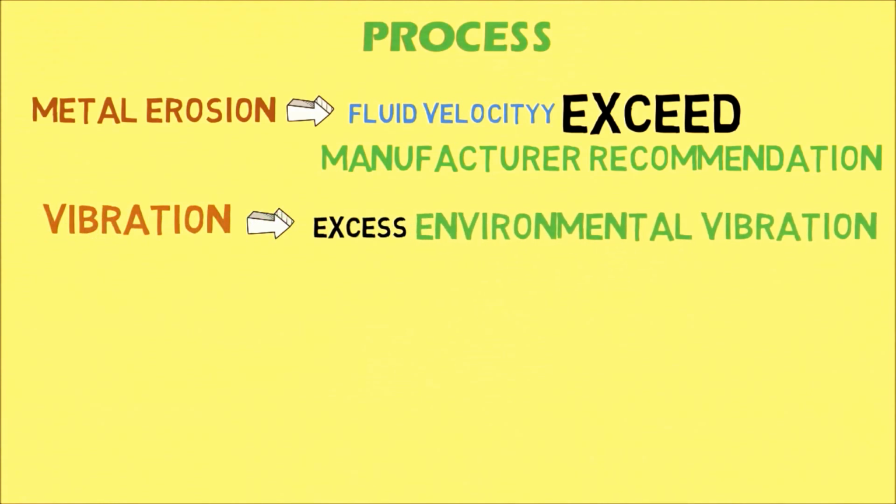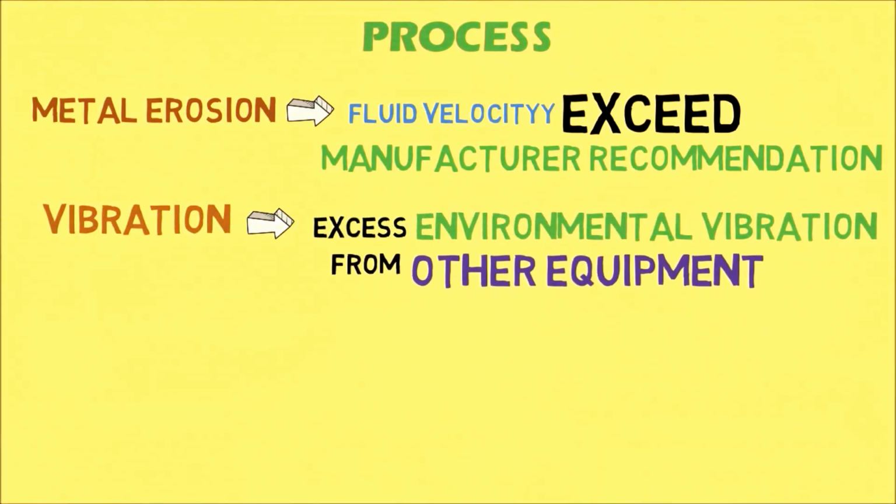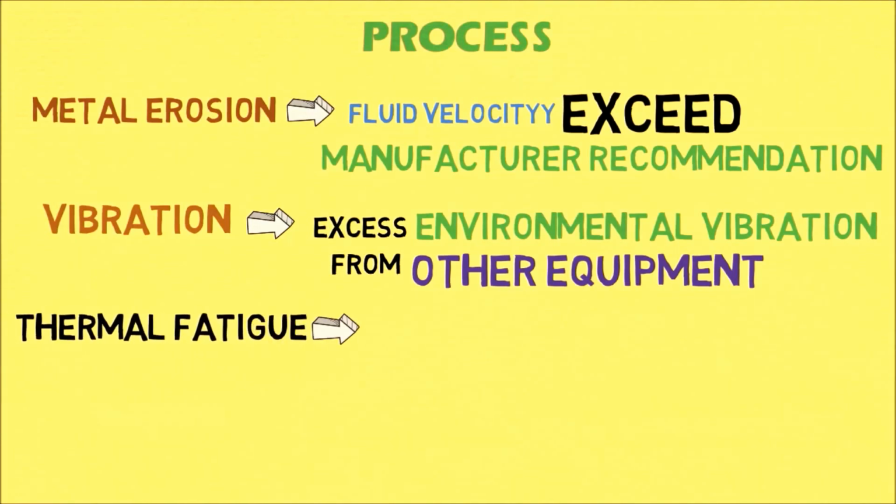Excessive environmental vibration from equipment including air compressors, refrigeration machines or other motors can cause tube failures that form as a result of fatigue stress cracks and/or erosion where the tube makes contact with the baffles. The third one is thermal fatigue.